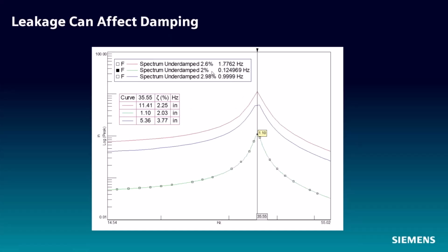So you can see the finer delta frequency, 1/8 hertz resolution basically, it matches up pretty well. 2% damping, 2.03 calculated in the software. However, we start to have divergences. So with 1 hertz resolution, we've got a significant difference, and 2 hertz resolution, also pretty significant difference in damping. And this is all due to the fact that the half power method, you need to have a data point at your half power points. And if you don't, you got to use the next data point. So that can cause some issues.